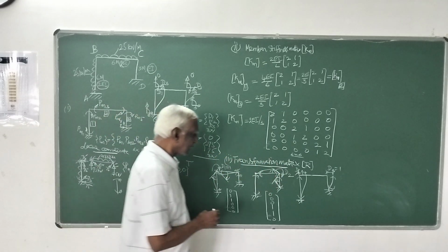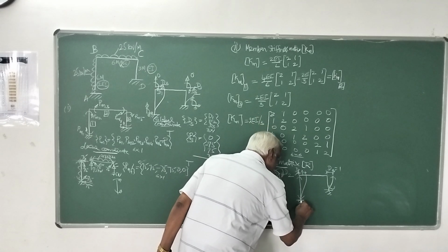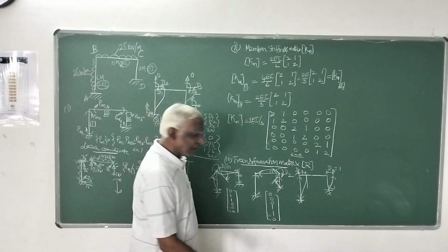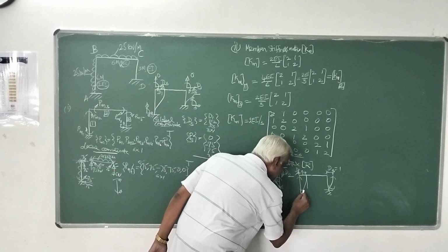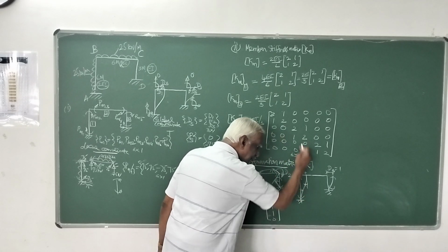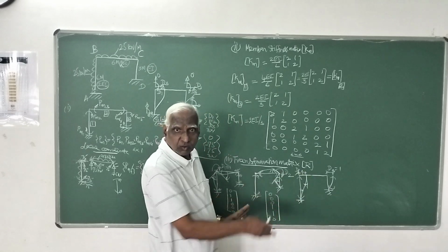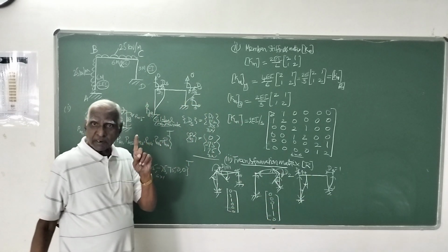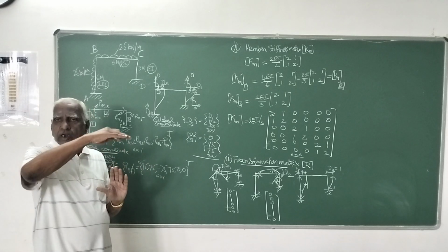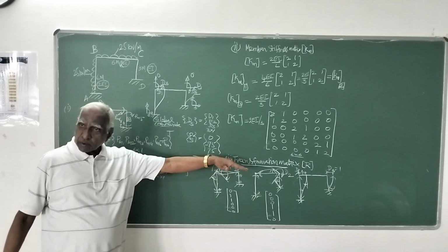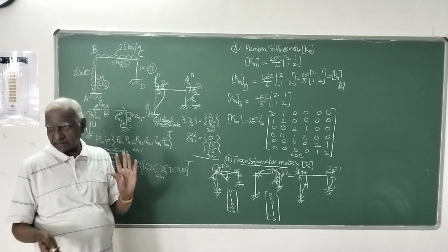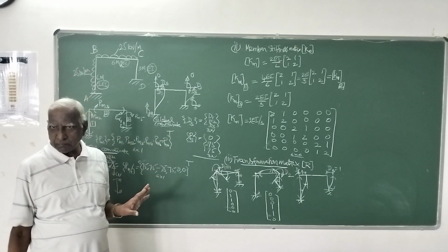Now here it is due to sway. How does the displacement occur? See here, displacement is there because this has swayed like that actually. So this has gone like that, this has gone. Originally it was straight, now it has moved clockwise. As per our sign convention in the slope deflection method, if you have a clockwise rotation of the original chord, sway is negative. Otherwise, it is positive.